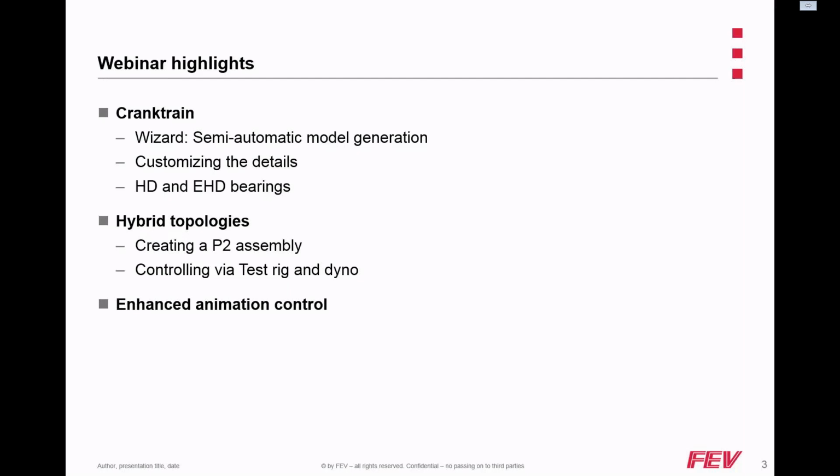What we have done is we have created a tool which helps you import the forces and the torques and place them correctly on every single tooth individually. If I look at the excitation forces, every tooth in my electric motor will have the axial force and the radial force acting on it throughout a cycle as a spline. And of course, that is how the excitation forces in my flexible body will be generated. I hope this is clear. If not, then please ask further questions on this topic.